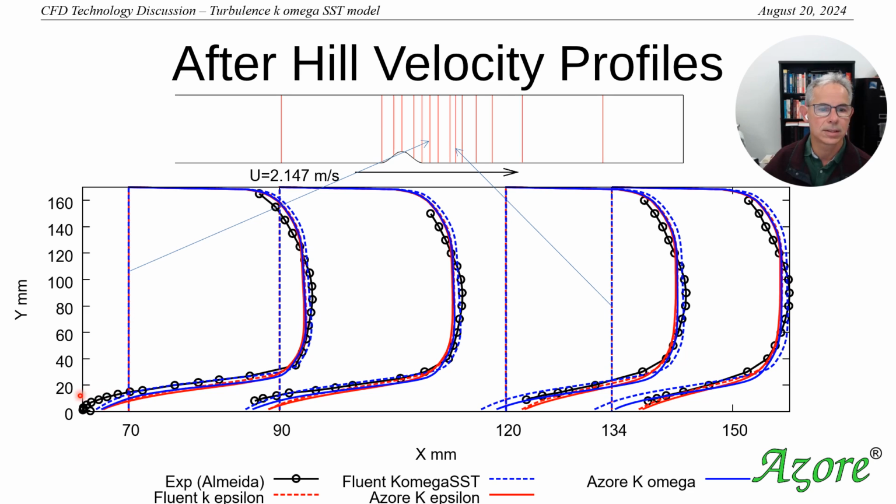And you can see there's a negative velocity right here where the velocity is recirculating. And then as the pressure recovery of that recirculation zone progresses, you can see that the recirculation zone and the negative velocities become smaller and smaller until there's really not much negative velocity left at all.